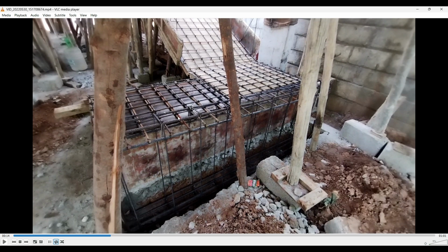So we have seen we have given 2 bars here, 2 bars over there. So this is basically a hidden beam. Whatever extra bar we are giving, we are giving only because we have to support the hidden beam somewhere. To support the hidden beam, we are giving all these ties, and at the bottom we have given again some additional amount of reinforcement.